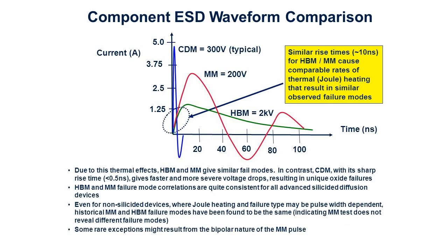Using waveform plots on different time scales, we compare the current waveforms produced by tests that comply with two ESD system level test standards, IEC 61000-4-2 and ISO 10605, which use different resistor and capacitor values in their test circuits. ISO and IEC HBM ESD tests are important for ensuring high electronic quality.